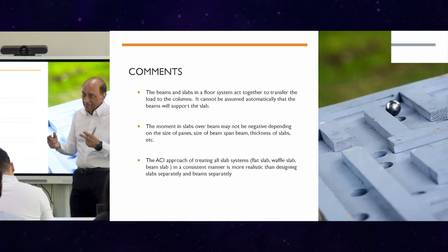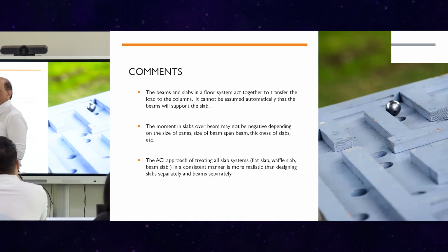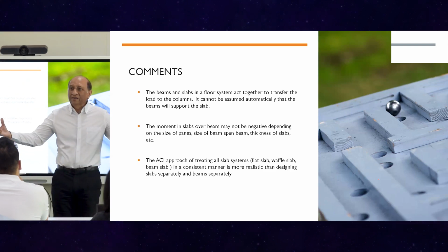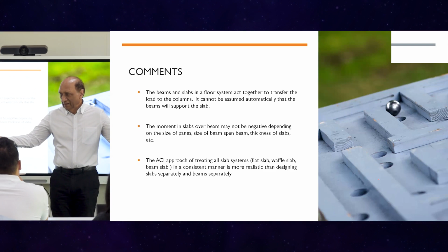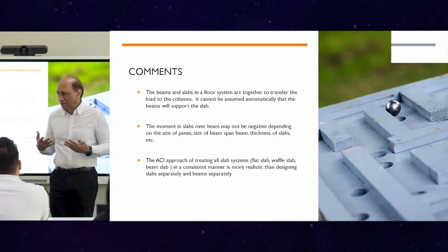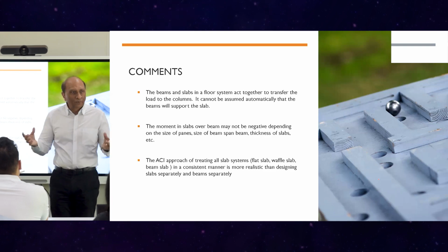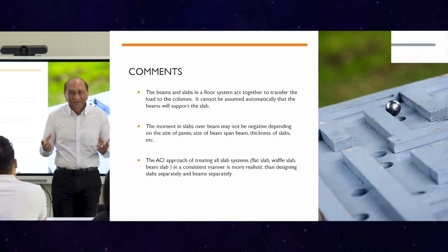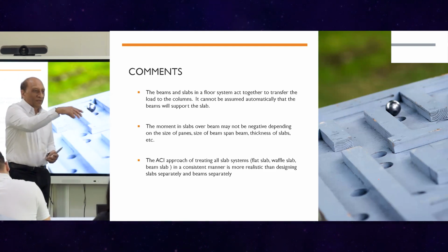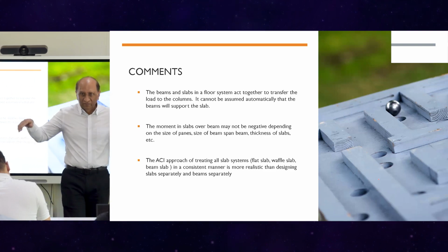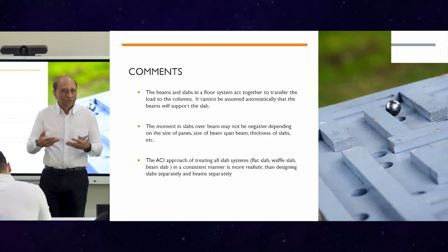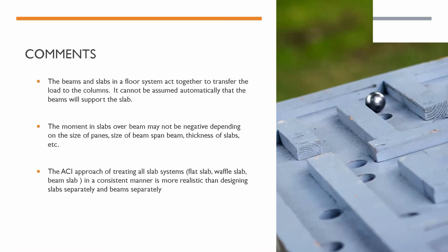But with post-tensioning, remember, we convert a two-way slab system into a one-way slab system. In one direction, we put the bands to carry 100% of the load. And then the slab in the other direction, because there are no beams, we can decide how the load will be transferred, depending on the distribution of the tendons. So we design the tendons in such a way that one side of the slab, without having a beam, becomes a support. Because we now have the ability to control the uplift and the forces in the slab to create a situation where it does not deflect.